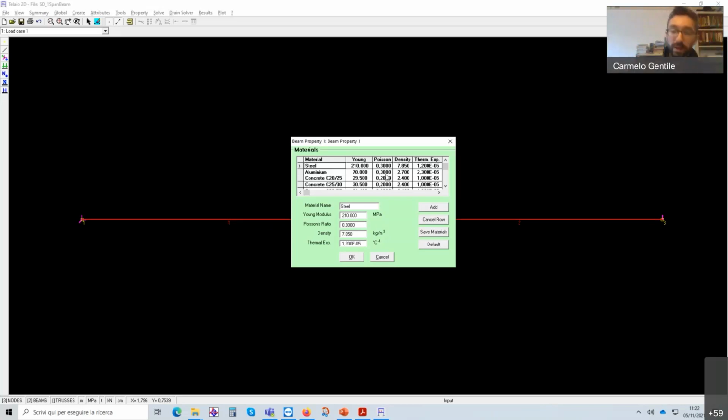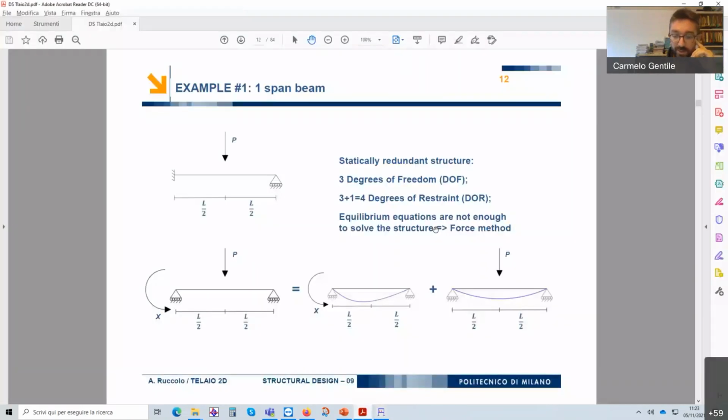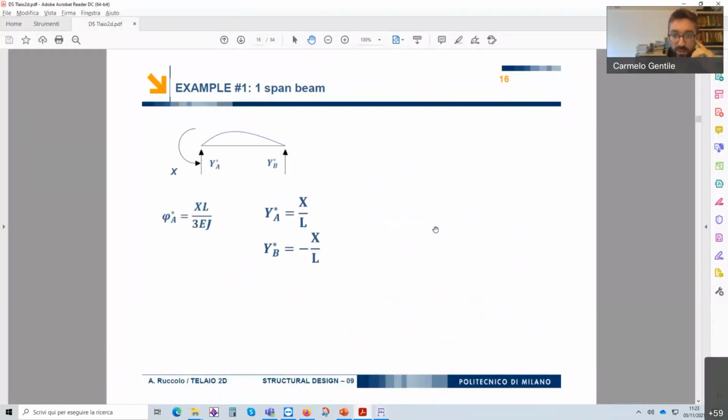And if you deal with homogeneous structures or statically determined structures, the distribution of forces inside the structure and the reaction forces do not depend on the material. Why? Actually I'm quite mad, because that's a tricky point that everybody forgets about, but you're obliging me to talk about it now.